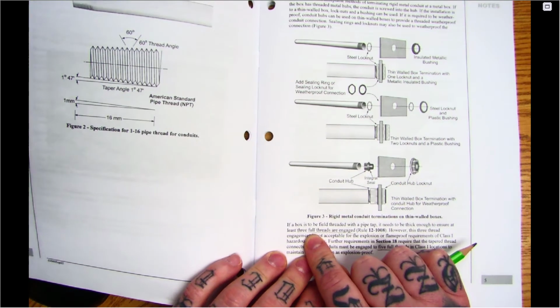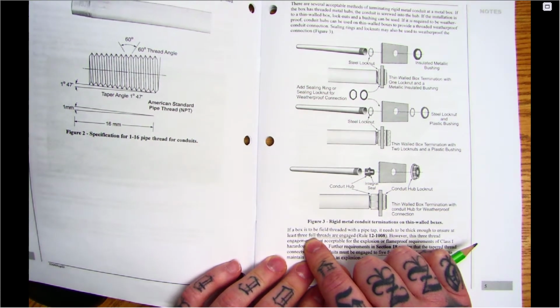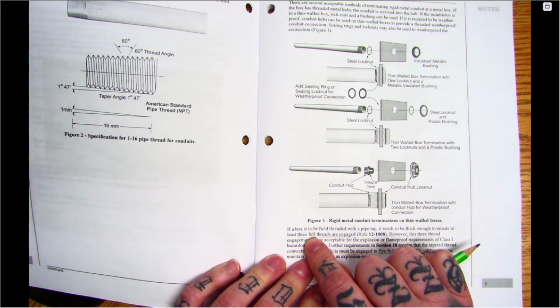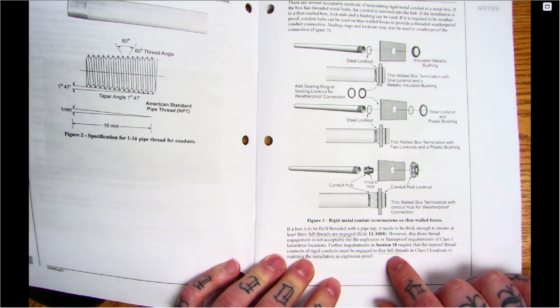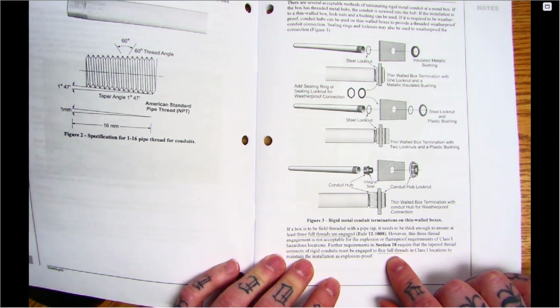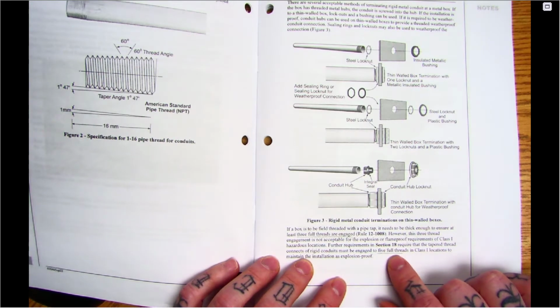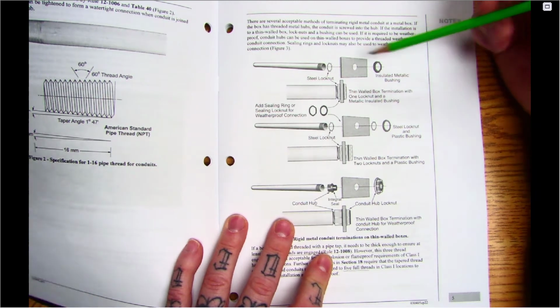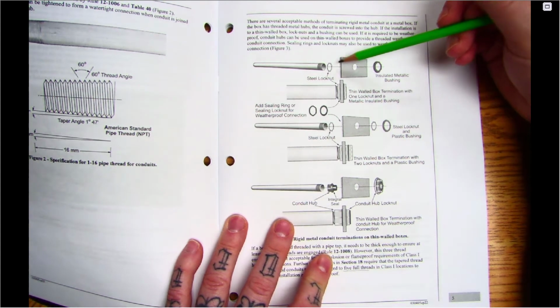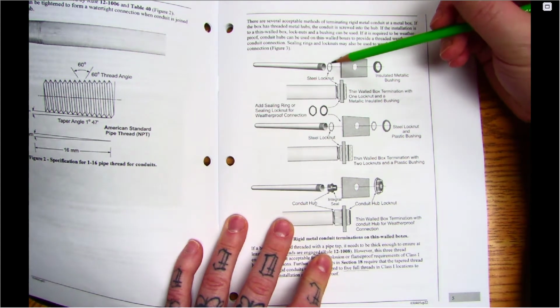Okay, so often we're the one bending, cutting, and threading this pipe, so we have to make sure that we have enough threads and that they're engaged. When they talk about section 18, which is classified areas, so potentially explosion areas, we need 5 full threads on those. Some terminology, again, we talked about this in grounding and bonding,